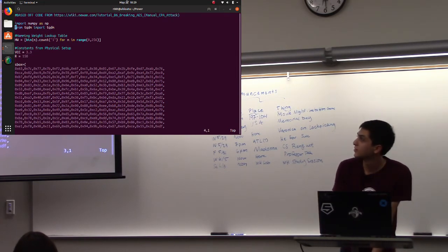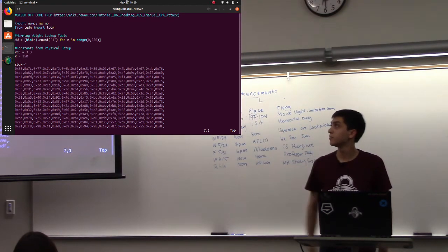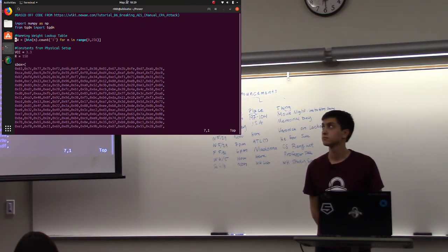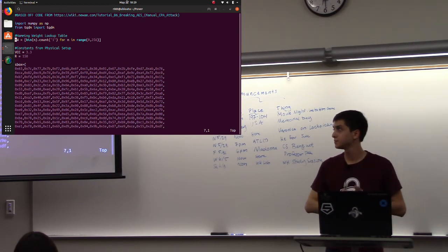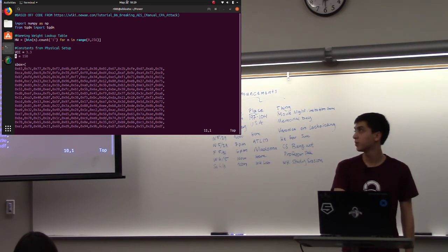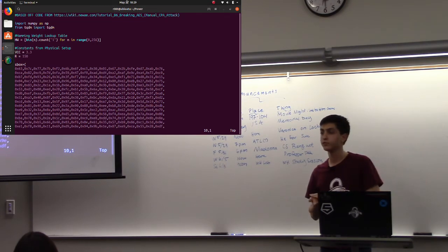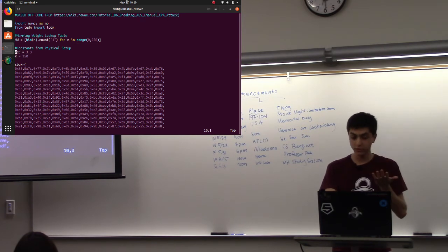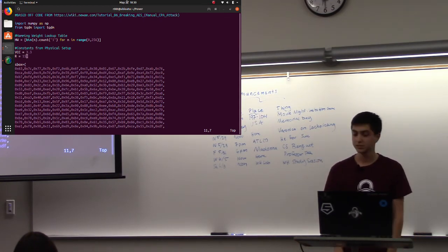Okay. So we're going to import some stuff. The Hamming weight lookup table: we're just going to generate a lookup table for all bytes, that is the Hamming weight, so we don't have to calculate it each time. It just makes some things faster. VCC is going to be our constant, which is the voltage we supplied to the device. It's whatever you do in your setup. We happen to do 3.3. R is going to be our resistance, which is that resistor we added. We just happen to use 150.